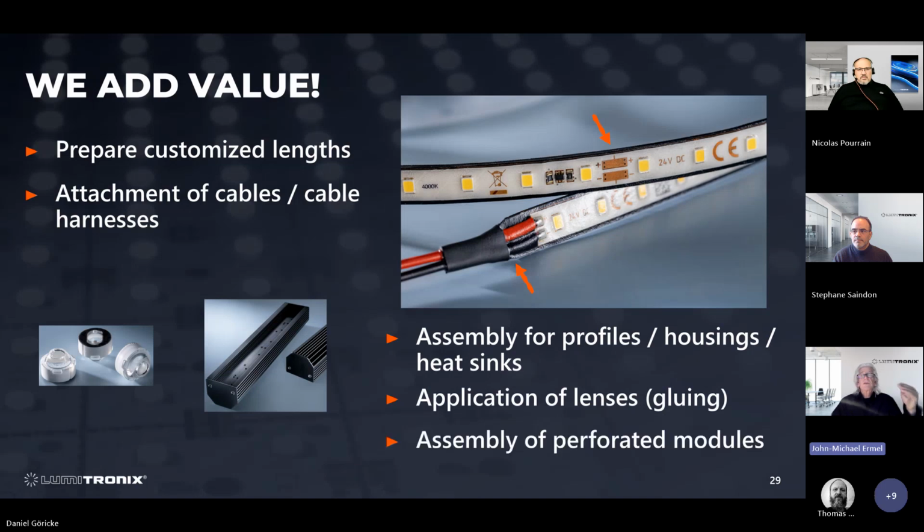But along the way, there are also things we can do even at the FPC substrate level, like having perforations in there so you can tear them or build them to your size, which is not so much relevant with cutting points or segments in a typical LED strip, but perhaps your FPC is actually a sheet of something.